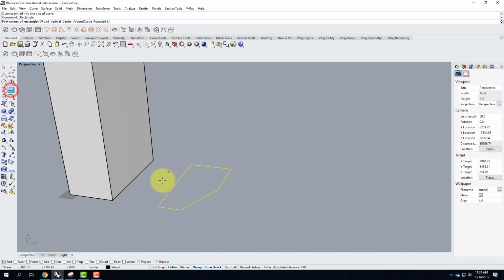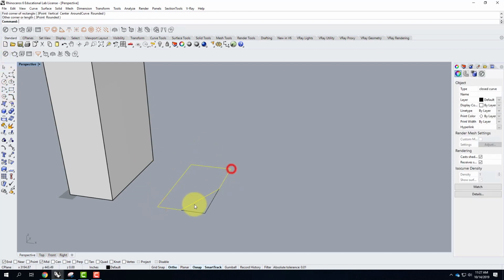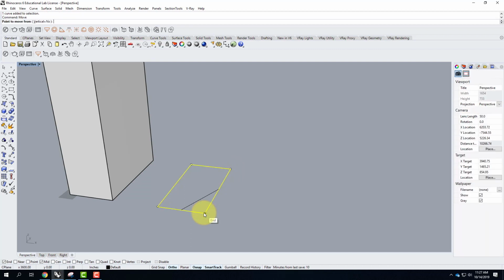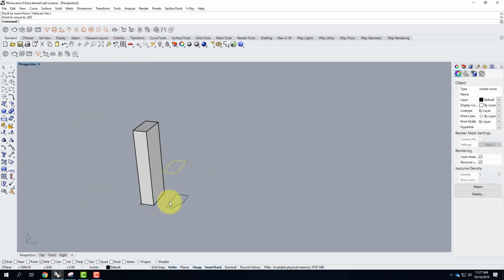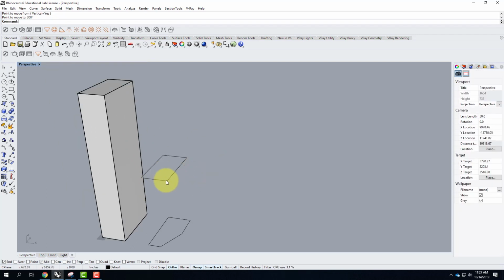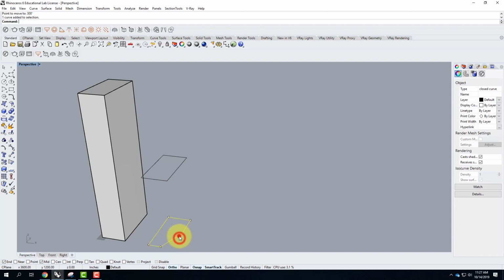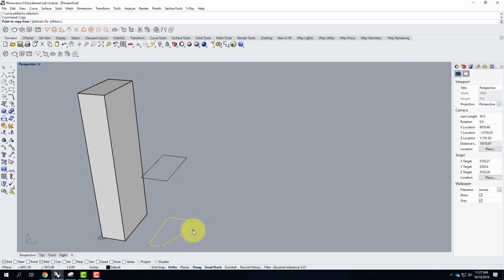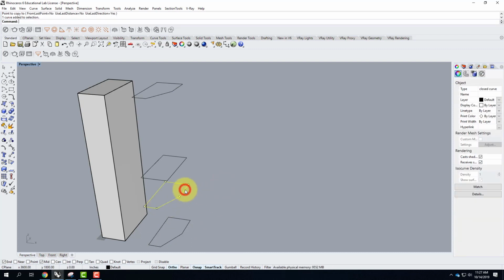And then maybe I'll create another rectangle. We'll move this, so I'm typing move, V for vertical, and we'll go up maybe 300 feet. And maybe that stays like that, and then maybe I'll take this one, vertical by 600 feet. Oops, don't need this one.